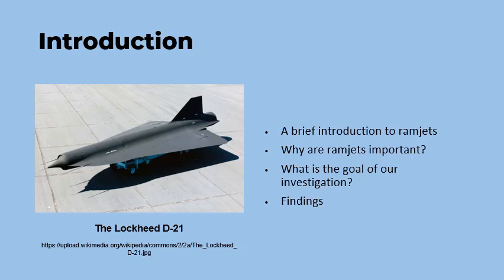Ramjets are a propulsion system utilized for high-speed supersonic applications. They're important because they provide a simple, efficient solution for atmospheric propulsion, where other options like conventional turbojets may fall short. The goal of our investigation is to understand the characteristics of the ramjet and its working principles using a MATLAB tool that simulates the pressure and Mach number through a ramjet nozzle or a converging-diverging nozzle. I compiled and compared various results from the tool with an analytical solution as well as empirical data in the form of normal shock function tables.